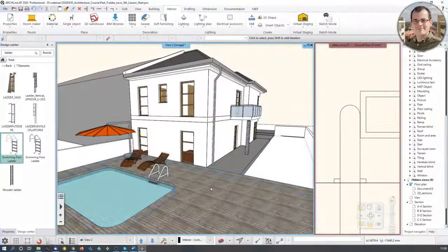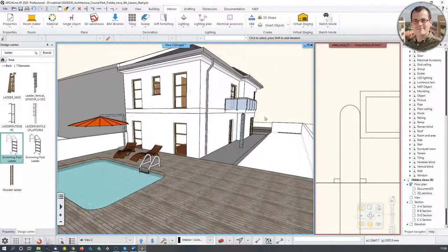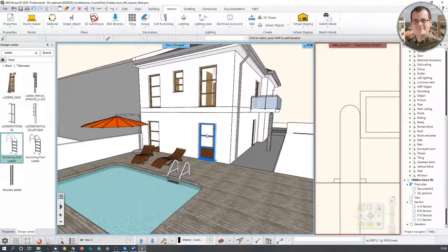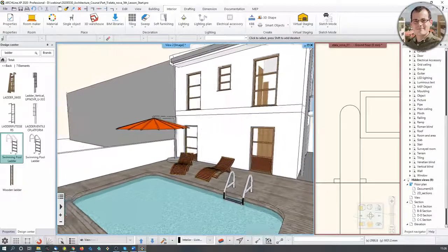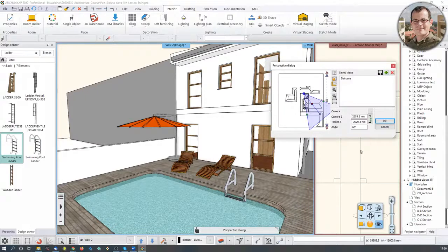That is important because I want to toggle back and forth between this view, the street view, and another view, which is actually the staircase. So how do we set them up? Well, there's a tool for that, obviously. It's under this eye menu. By the way, here's the toggle between axonometry and perspectives. Now we are in perspective, and if we click on the eye, we can set that up.